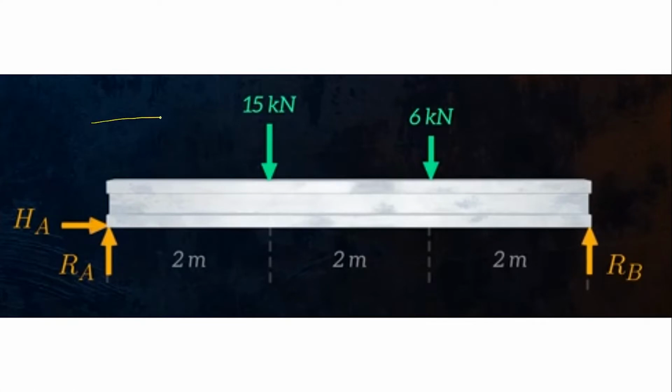As a reiteration, we have a simply supported beam. We have here a fixed support, and the other is roller. We were able to identify that here the reaction is vertical and horizontal because it's fixed. Here there's a free movement of rollers going left and right, so we don't have a horizontal reaction. The only reaction we have is this.